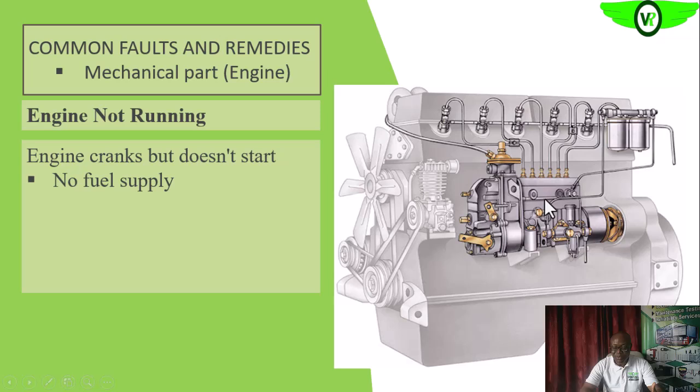Like we discussed in our earlier session, if the fuel is not delivered at the required pressure to these nozzles, the nozzles will not open up. Are we getting it? It could also be that your filter is plugged. The fuel is not even delivered to the pump at the required pressure for it to pressurize from there.